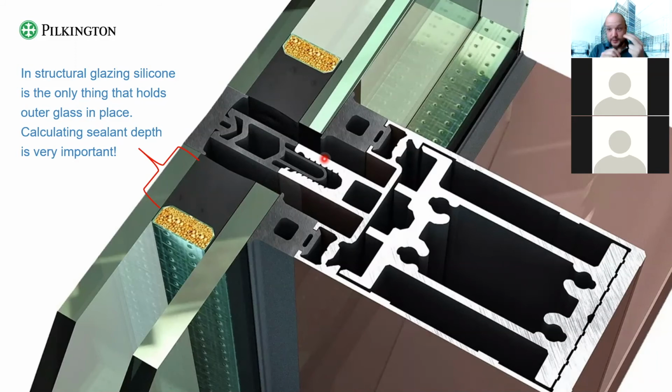What is the spacer distance? The place where the IG units will be used, I mean the geographical place, like Moscow. Then you have to provide the building height on which it will be used, in order to estimate the wind loads. Of course, the installation angle, whether it be vertical or at some inclination, back and forth.